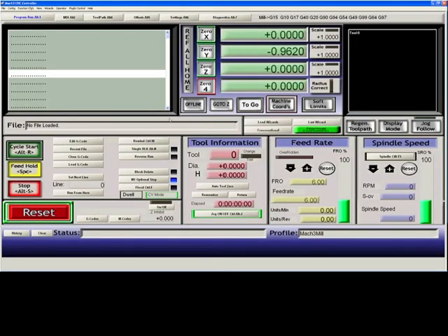That's it for the most common problems in getting Mach3 to actually put out. A good way to check to see if your printer port is working is to use that auto pin input setup, because it will at least tell you if your printer port is working. If that routine works for you, your printer port is valid and your motor signals are likely going out, but your breakout board may be missensing the charge pump input, so you want to read the documentation on your breakout board to make sure that the charge pump is not your problem.